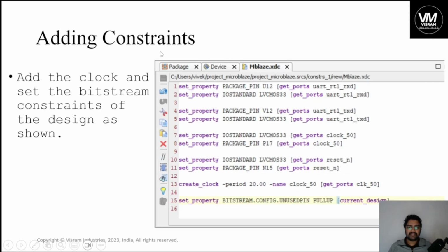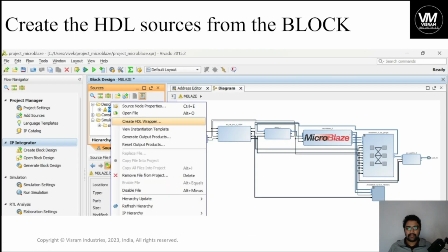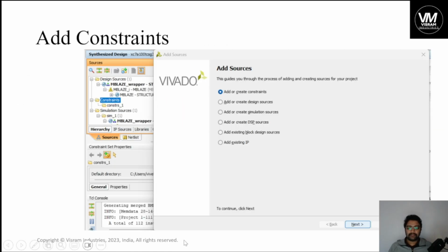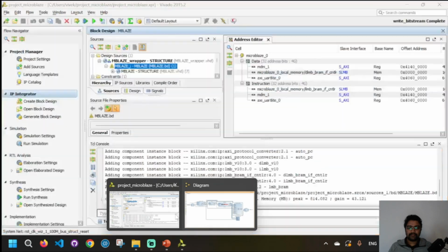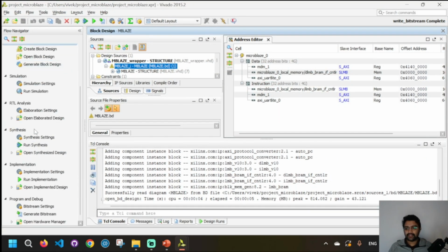And in the design layout here, you can drop down this. After you add the constraint file, you can drop down this and you can check for IO planning. So, like this. You click after synthesis, right?